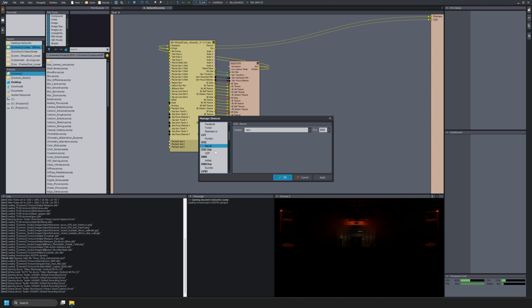Finally, we will scroll down to our camera tracking section. Find Axibridge. You just need to select the format that you set up in Aximmetry Gateway. I used Axibridge. Once Axibridge is selected, select Add in the upper right-hand corner. Use the adapter dropdown to select the IP address. I left my UDP port in Aximmetry Gateway set to the default 17501. If you change the camera tracking UDP port, you'll need to update that here. Now I can select OK to create that Axibridge channel.